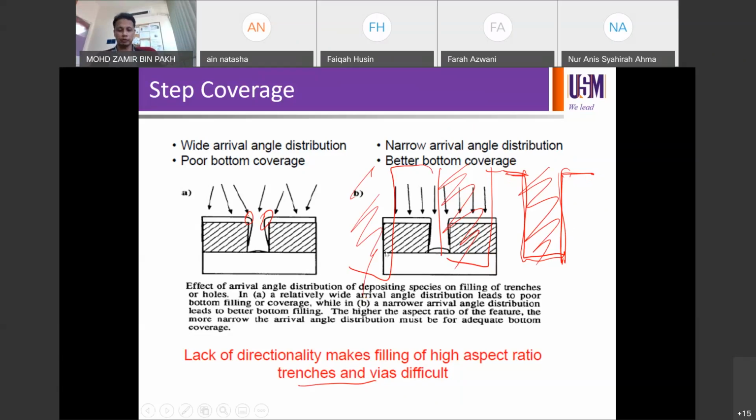You can introduce some annealing process after the deposition if you can, or in fact you can also do substrate heating, if you remember substrate heating. The substrate temperature setting is actually a heating process. You can do heating while doing the sputtering process to minimize this problem, because when your atoms arrive on the structure, they pretty much land and stay put, and they don't go anywhere else.